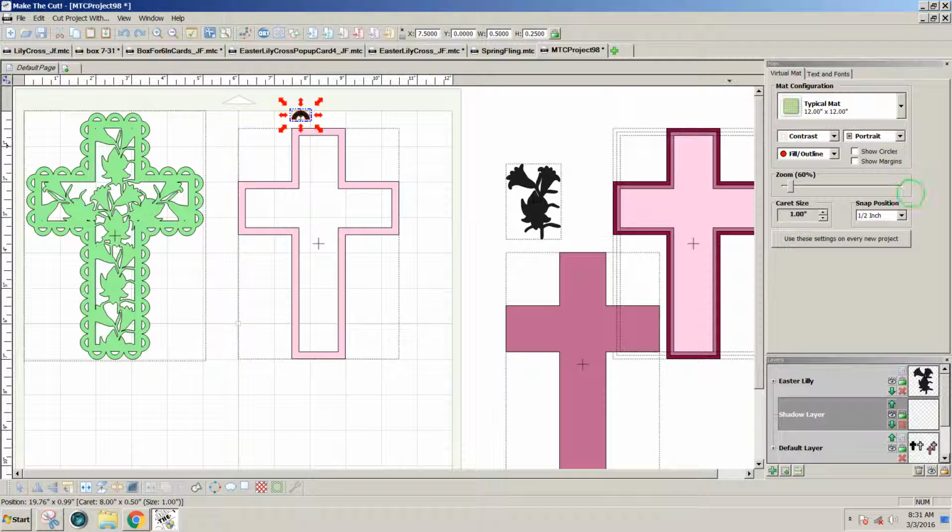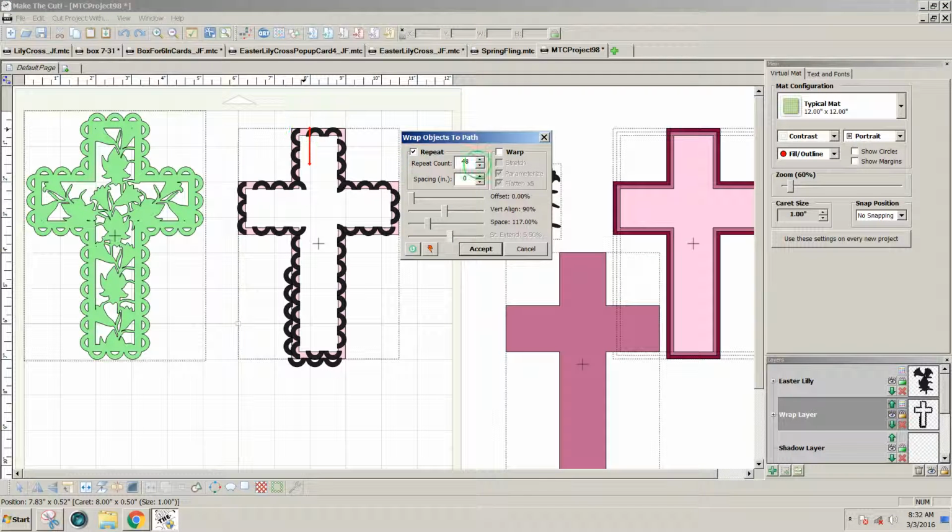I'm going to turn off my snapping, and I'm going to drag it just till it crosses the outside line and the cursor changes into that square, circle, triangle. Then I'm going to release the Control button, release the mouse, and then I'm going to make some adjustments in the positioning and the number of shapes that I get.